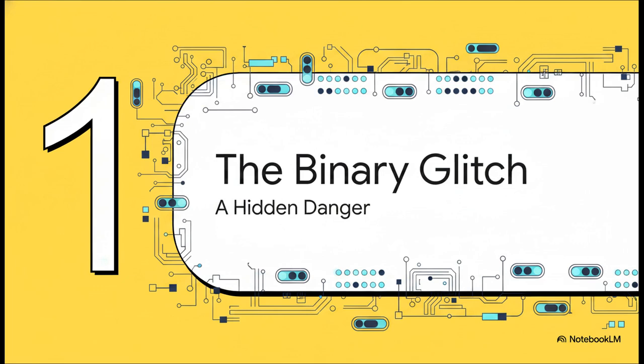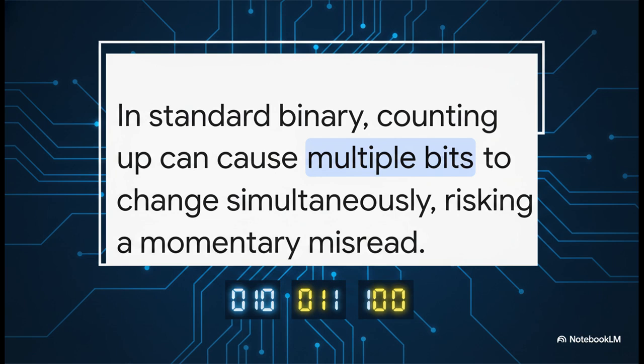The binary glitch. So what is this hidden danger? Well, it all boils down to a really small but absolutely crucial detail in how we represent numbers using those on and off switches. Bits. So, you know how standard binary works, right? Every number has its own unique pattern of ones and zeros. Simple enough. But, and this is the key part, going from one number to the very next can get surprisingly messy. Sometimes it's easy, just one bit flips, but at other critical moments, a whole bunch of them have to change all at once, and that is where things get risky.